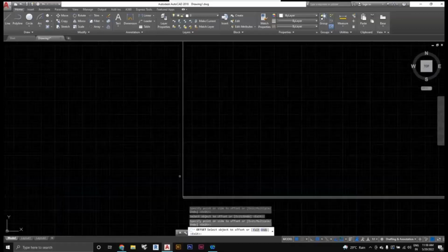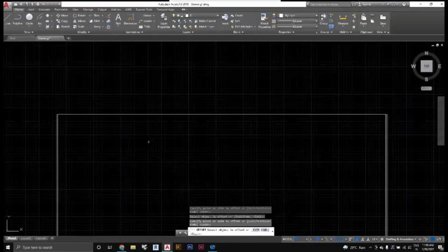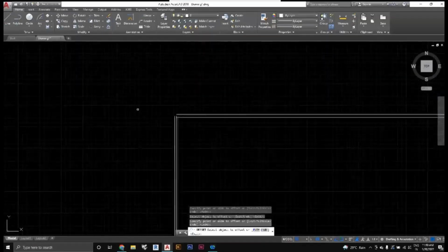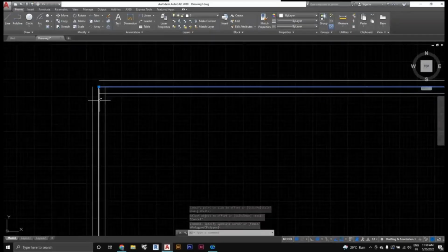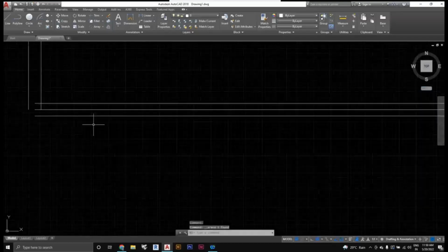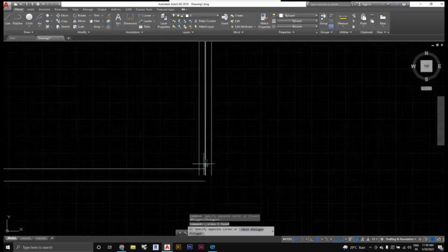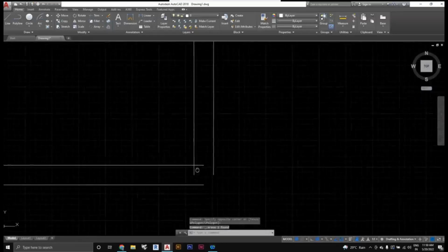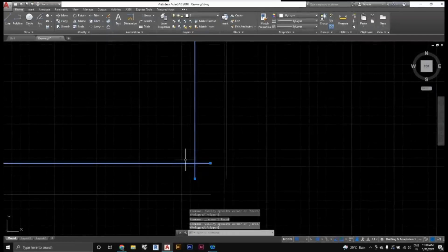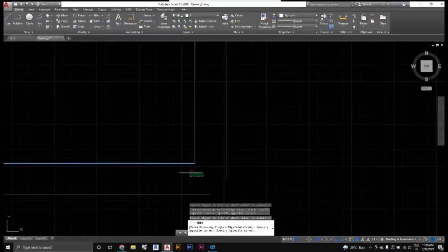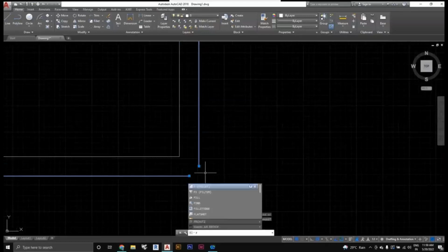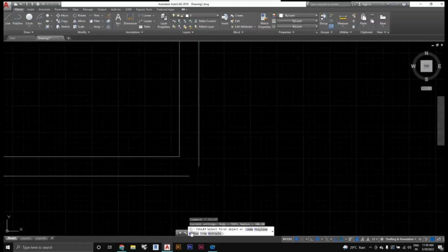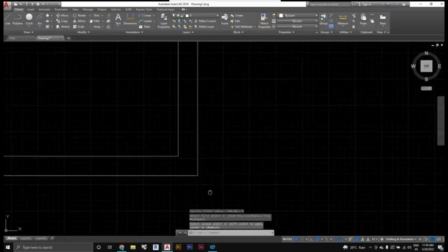So you simply make the wall in double line plan in no time, and you can erase the interior lines that are formed by just selecting them and pressing delete. You can just delete the center lines formed here. With the help of the trim command, you can trim the edge that is protruding outside. Use trim, TR, spacebar and click it, and you can join these two with the help of fillet. You can type F and then spacebar, then give the radius as 0 and press enter.